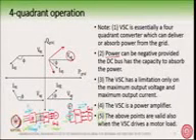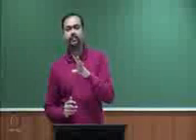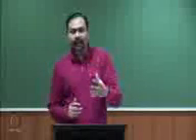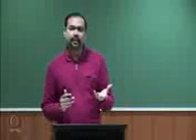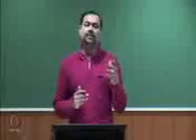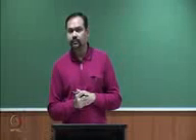Okay, you have the I rated, you may have some I transient rating for a certain small duration, but normally we keep it as I rated. So you have an I rated and you have a V rated, that is the voltage that can be produced, which is dependent again on the blocking voltage of the devices. So the voltage source converter has a maximum output voltage and maximum output current.